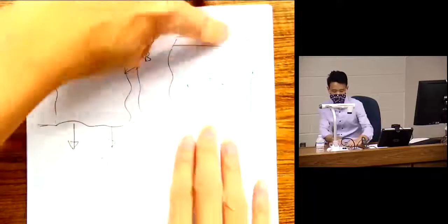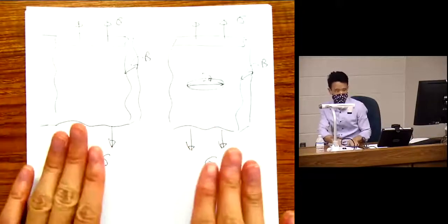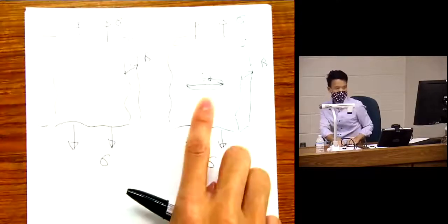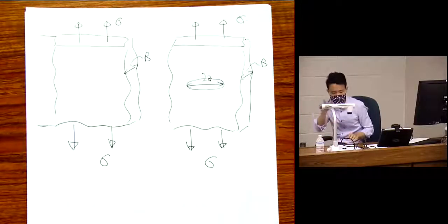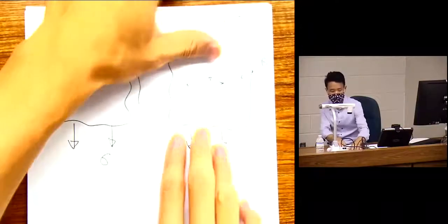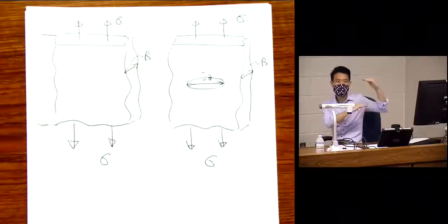I load it. This is two different specimens, by the way. Two different specimens. This one I make a crack inside, 2a. I measure it, I make a crack, and then I drill a hole, I make it crack here. So I know exactly it's 2a. And I load it with the loading grips to sigma, and I stop there. I don't move anymore. Okay.